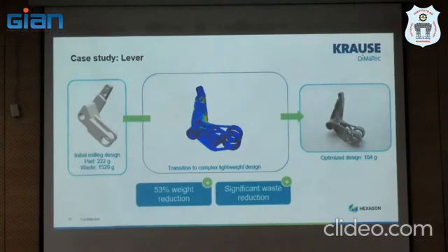But in the manufacturing, you are able to precisely and locally control the structure, and graded properties can be developed. That is possible. You can design for a 5 to 10% change by varying the printing strategy, but that alloy will have its own properties. In case you look at a disk, you want an equiaxed structure; in a blade you want directional solidification. This is possible. That means you are changing the entire range of properties in a given material by changing the structure. That comes in the post processing, as you mentioned.